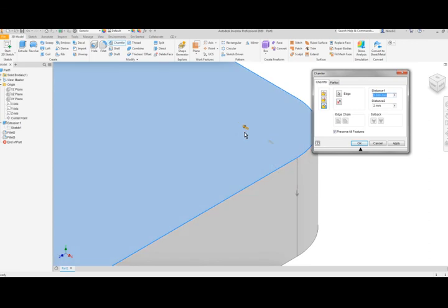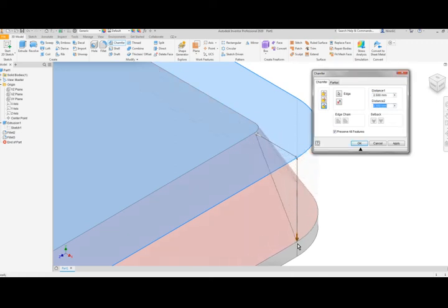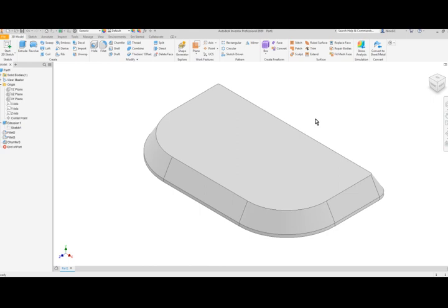If it passes that point, then it will not form anymore. The same thing with if I click now the vertical arrow, I can just bring it down to as far as I need it. And if I surpass that, once again, it will fail. The reason for that is that there is no material that it can actually manage to remove at this point. So once again, we can highlight each one and also manually type in the values. Let's click OK, and now we have that. So there is our chamfer.